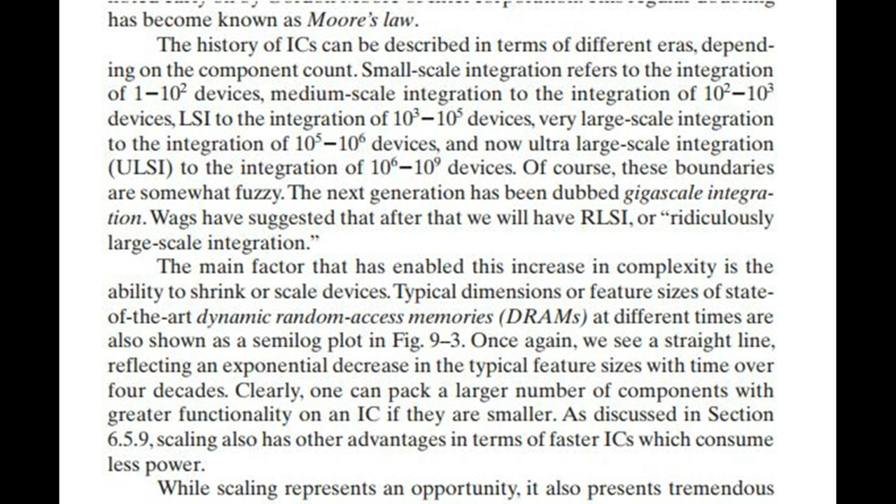Small-scale integration refers to the integration of 1 to 100 devices, medium-scale integration to the integration of 100 to 1000 devices, LSI to the integration of 1000 to 100,000 devices, very large-scale integration to the integration of 100,000 to 1 million devices, and now ultra-large-scale integration, ULSI, to the integration of 1 million to 1 trillion devices.